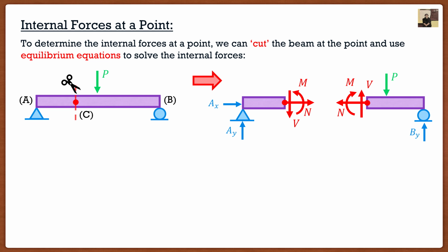The only thing that really gets students is that shear force, because typically, and I think this is always ingrained into us, we always like to analyze the left-hand side. I'm not too sure why. So if we're analyzing the left, our shear is going downwards, but most students always assume that left is positive, so they put it upwards, but our shear is going downwards on the left.